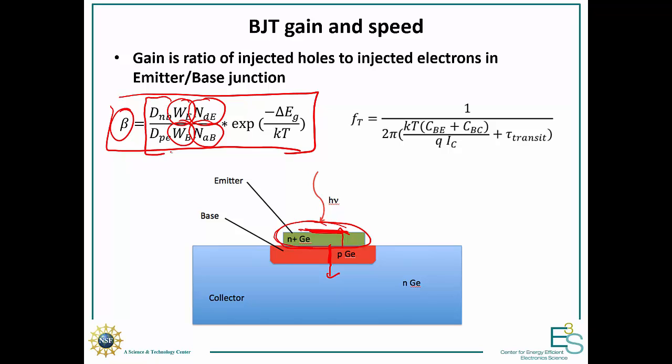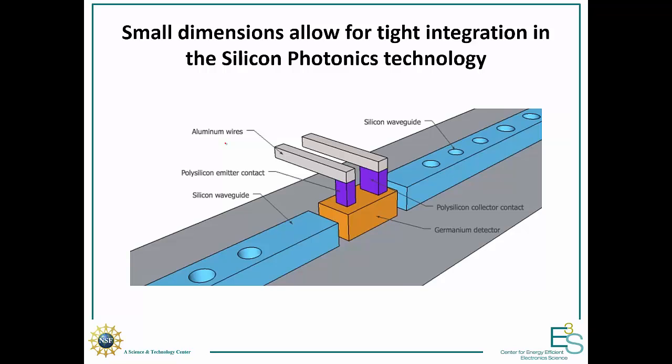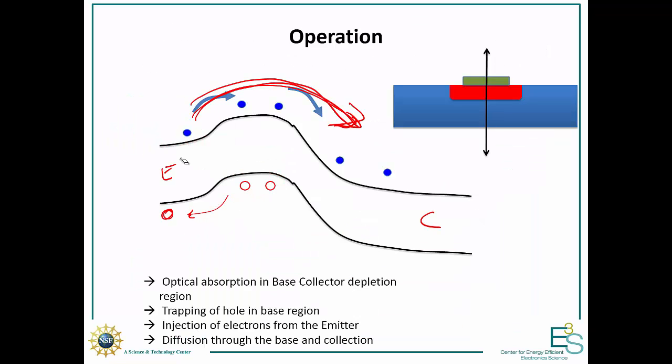This here is the emitter of the ratio of the diffusion coefficients for electrons and holes. I won't go over that, but you can find it in any good textbook. Now, this final term here is if ever you have a heterojunction, and you need to make your heterojunction right, meaning, imagining we had silicon in the base instead of germanium. Well, silicon, as I drew the band gap earlier, has a larger band gap, and most importantly, that happens at the valence band.